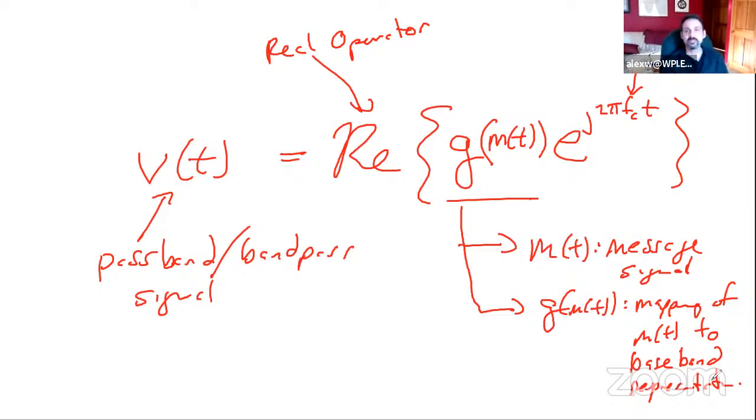There are all these techniques that take analog information, not digital, located at baseband, map it by a certain representation, and then move that information up to passband, exactly like AM radio. And then there's also the digital form, like what we use in cellular telephony or Wi-Fi, for instance phase shift keying, PSK, amplitude shift keying, ASK, and all that.